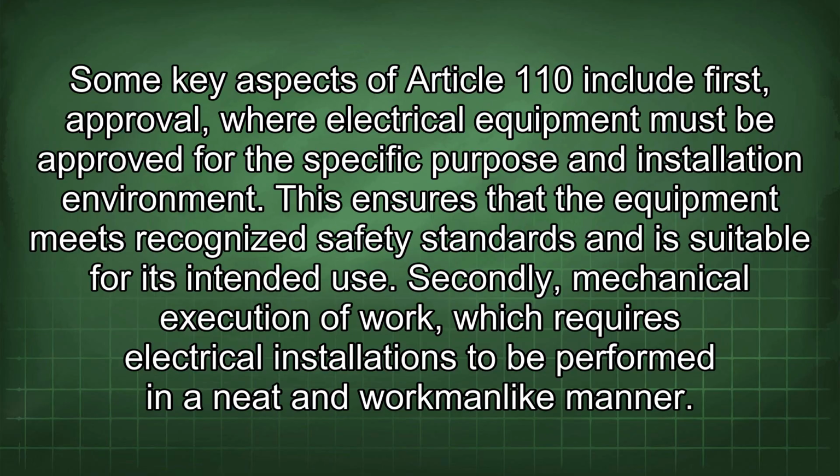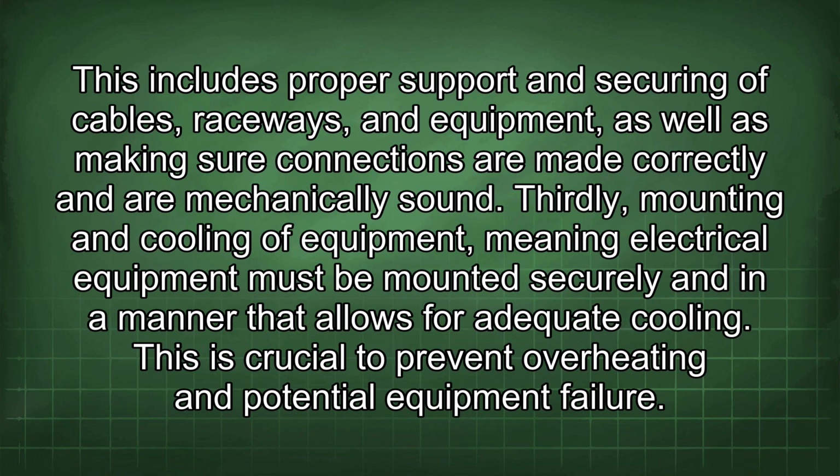Secondly, mechanical execution of work, which requires electrical installations to be performed in a neat and workmanlike manner. This includes proper support and securing of cables, raceways, and equipment, as well as making sure connections are made correctly and are mechanically sound. Thirdly, mounting and cooling of equipment, meaning electrical equipment must be mounted securely and in a manner that allows for adequate cooling. This is crucial to prevent overheating and potential equipment failure.